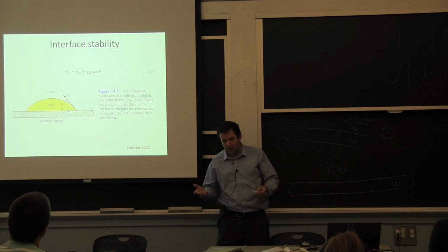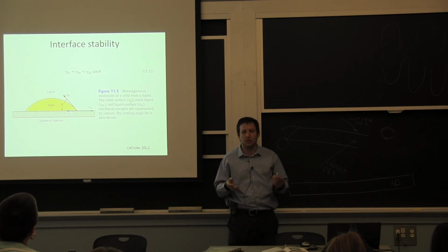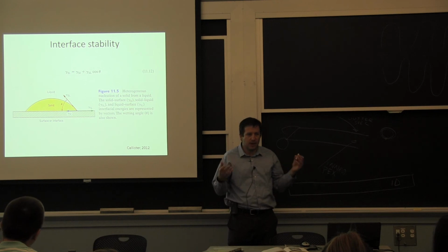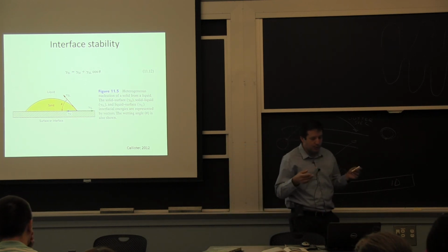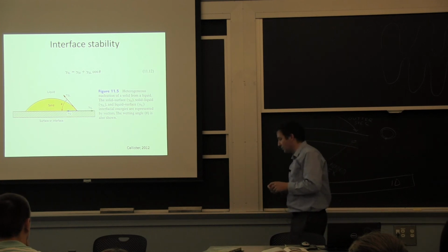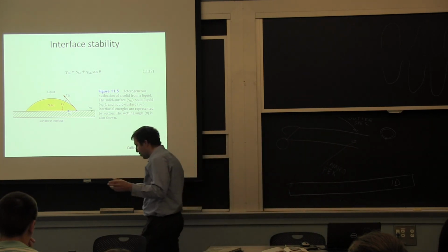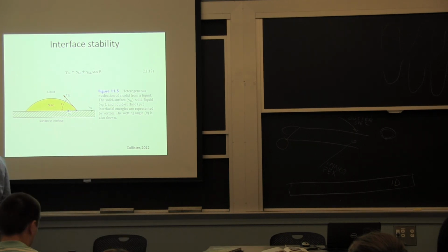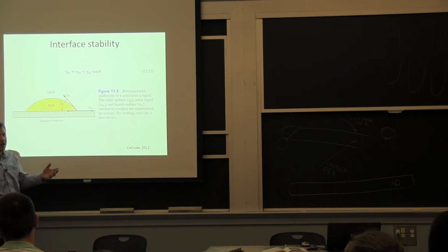Now that we know the phase diagram, say, okay, we're transforming. We talked about that you need a nucleation. If you didn't have any mold or anything for your material to grab on, it wouldn't solidify. So there was a question after last class about putting a coating, zinc for example, on the mold, or doing all sorts of little modifications to the mold. And I talked about roughness to try to improve the nucleation, to have as many crystals as we possibly can. I wanted to go back essentially to call on a very fundamental phenomenon.